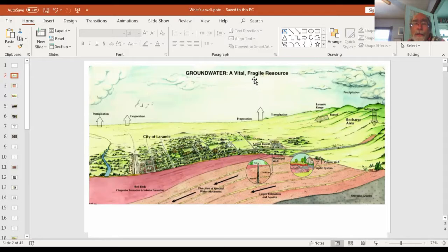Municipal wells tend to be deeper, penetrating multiple beds within the Casper. So we have a sandstone, limestone, sandstone in this particular picture. The municipal wells are bigger. They have pumps in them capable of extracting up to 1,500 gallons a minute. The domestic wells are of course much smaller and typically shallower because they don't need access to that much water. So they typically will access 1, maybe 2 of the different units within the Casper Aquifer.